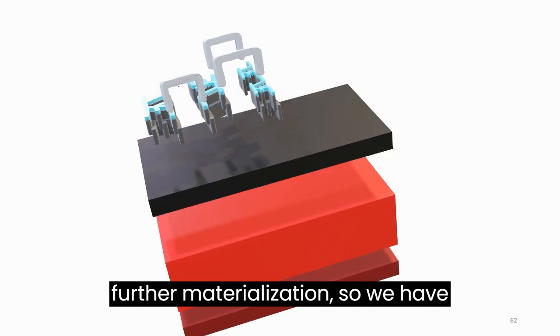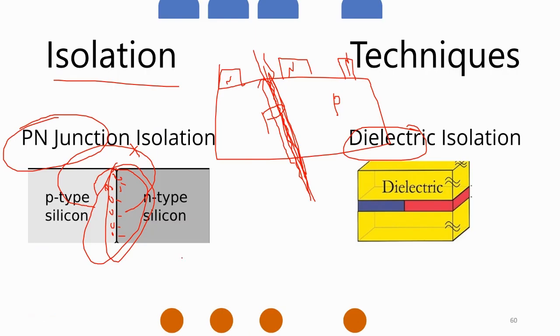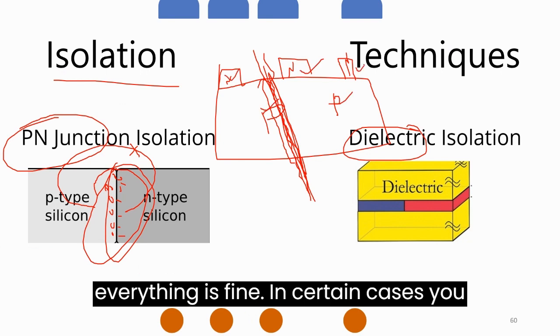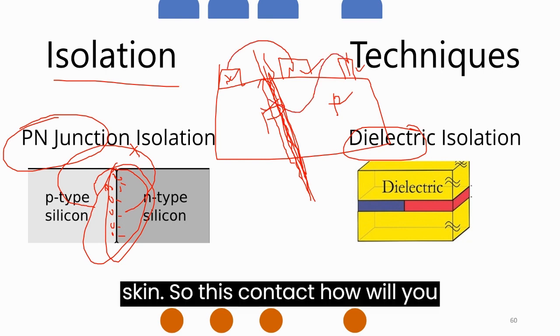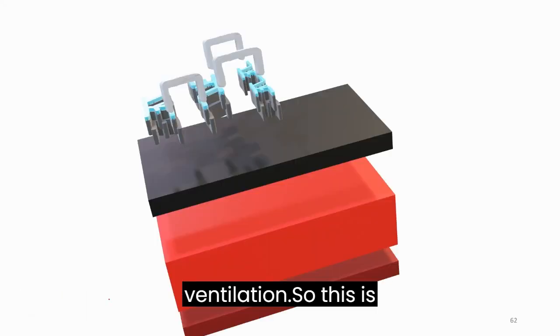Proceeding further, metallization. We have formed these layers, right? We have formed this N, P, N, P, N, everything is formed. In certain cases, you need this N to be connected with this N, this P to be connected with this N. So how will you make this contact? To make that contact, we use metallization, right?